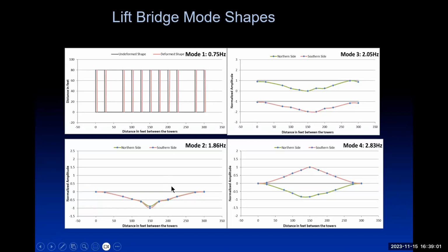And again, we have modes of vibration which are similar to the ones that occur in the main span, because they're the sort of thing that's expected of a bridge deck. But in this particular case, we had something in the middle, which was a stiffness anomaly.